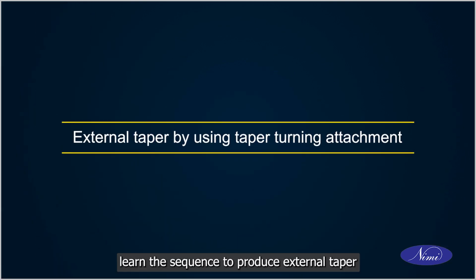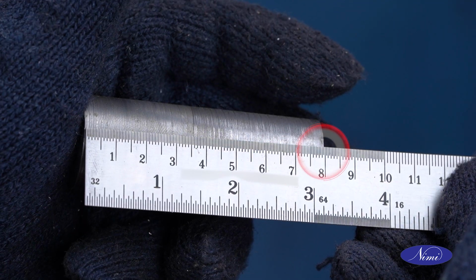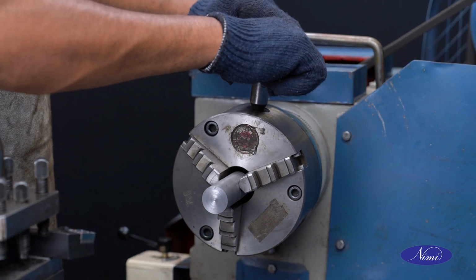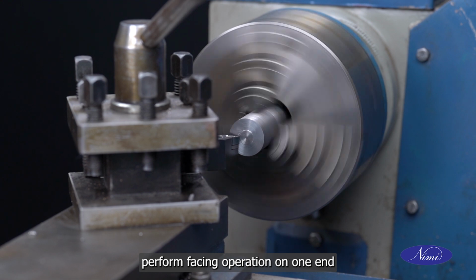Let us now learn the sequence to produce external taper by using taper turning attachment. Check the size of the raw material. Hold the material in a 3-jaw chuck. Perform facing operation on one end.